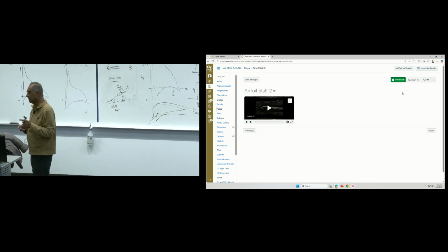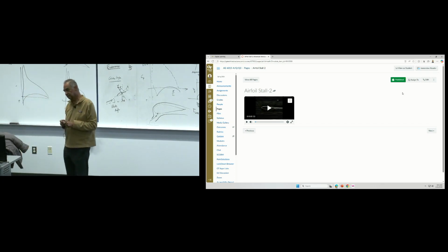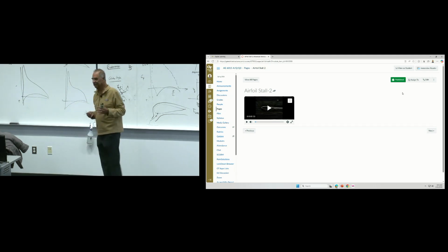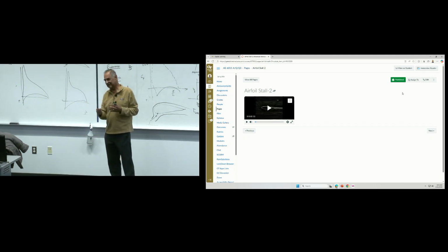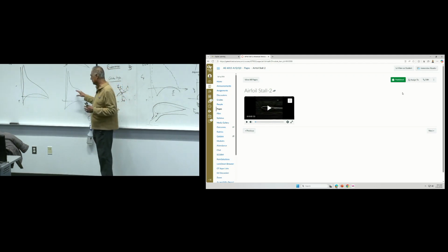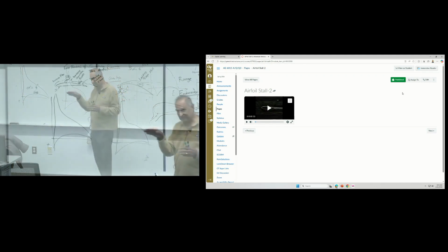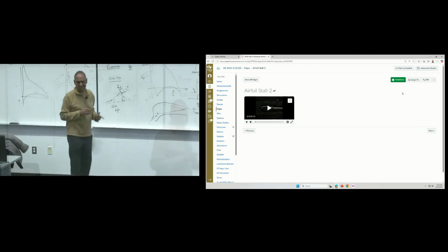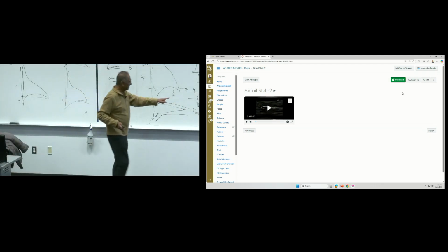Okay, yeah. Can we say that in a thin airfoil, the transition point is similar to, or closest to, the separation point? Since they are two different phenomena, it's kind of hard to categorically say that. For the transition point, we have to look at where the flow separates laminarly or at least has an inflection. So we have to focus on inflection. It's possible to have an inflection without separating. Okay, so inflection without separating.